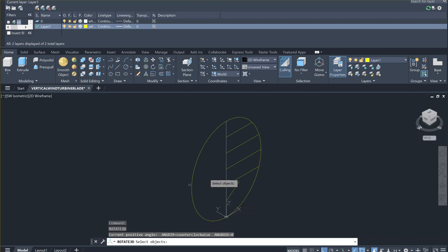Now this time I'm choosing the second one from the bottom, second line from the bottom, click and enter. Now it says what axis? Well, z-axis again, click. It says select the point on the z-axis. I select end of the line where it intersects with the z-axis. Okay, now it says rotation angle. Rotation angle this time will be 2 times 24 degrees, 48 degrees. So I type 48, enter. And rotation is already made for 48 degrees. Cool. And then I cross the 48-degree rotation.